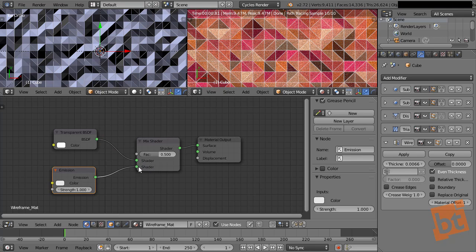All right, this means that in Blender the things that are more to the bottom are actually on top of the previous one. All right, it's like this is the first, this is the second, this is the third, which means that the third is on top of the second one. All right, I don't know if that's clear, but the more to the bottom of the list, right? Same happens with modifiers and with layers here in the mix nodes. The ones that are at the bottom have an effect at the ones over the ones that are on the top, right? So I hope that's clear.